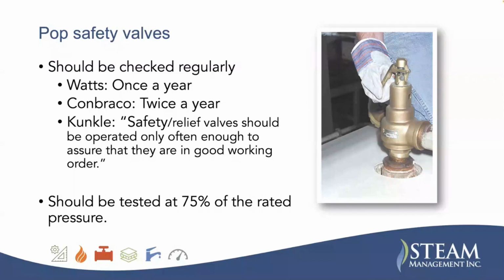One of the other things that the technicians also forget about is that to properly test a pop safety or relief valve, they want you to take it to 75% of the rated capacity. What they are saying is that if it's a 15 psi relief valve on a low pressure steam boiler, you have to take it up to 11 psi, test it, and then drop it down to whatever pressure you're operating it at.